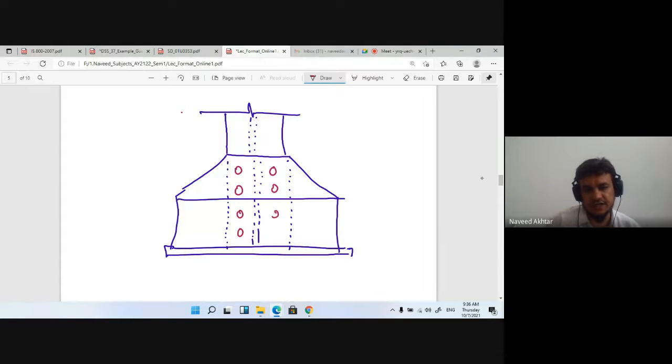So 8 bolts are connected with the column and 8 bolts are connected with the angle to the base plate. So this is nothing but your design, and you can write down the design summary. The thickness of the base plate is also 16 mm. This is the longer leg,